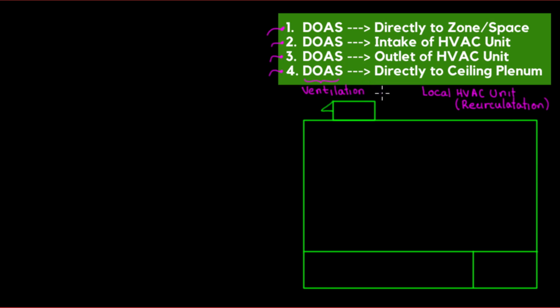So as you can see in here, this is the rooftop unit, and I'm gonna put in here, air is coming out from outside air. And of course, this unit is going to have heating and cooling coils. So this unit also provides conditioned air, because if it's summer, 110 degrees, it's not just gonna bring all the way inside the same temperature, the same humidity. This is going to also condition the air, and then we're gonna have in here conditioned air that represents the outside air in the unit.